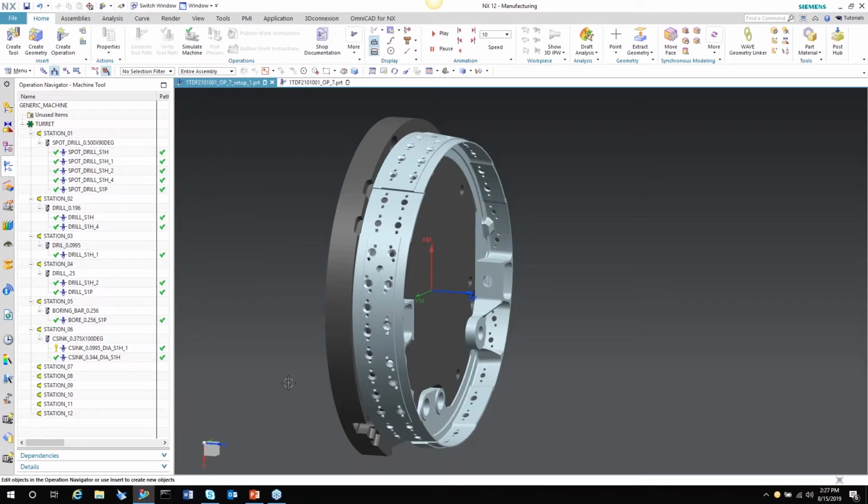Group them together automatically through feature recognition and feature-based manufacturing. So what I would like to see happen after this demonstration is that all of you go out there, pick a previous part that you've already programmed that has a lot of 2.5 axis features, and then do this feature recognition on it. Do the group features, and then generate the operation, and see what you get out of that, and then remember how much time you had in programming it before.